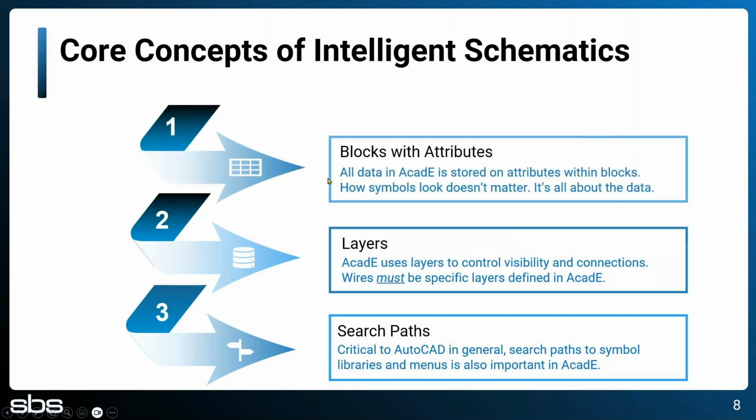And finally, the most important one we work with is blocks with attributes. If you haven't used those before, that is the core basis of how the software is storing and maintaining the data in the drawings: blocks with attributes. And again, a very generic AutoCAD tool that's been around forever. So you don't have to worry about being backwards compatible. You don't have to worry about taking your drawings and sharing them with non-SDS-P&C Toolkit or non-AutoCAD Electrical people. We're still just blocks and attributes in the software.